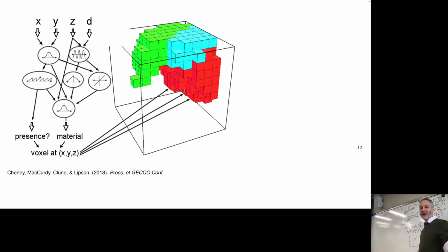So this CPPN is going to drop voxels inside this empty cube to construct the 3D geometry of our soft robot. While the CPPN is dropping cubes, the second output neuron is rounded by an activation function that rounds that value to an integer that is either 0, 1, 2, or 3. There are 4 possible values for the second output neuron.